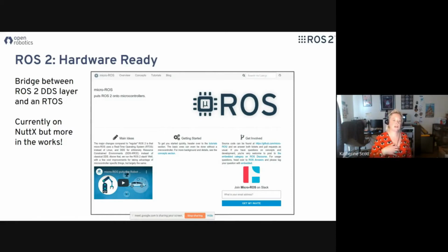And so within the past year or two, this project has started taking off, where you can basically build a baked-in ROS interface to all sorts of different kinds of microcontrollers. So if you're interested in, like, say, ESP32s, or some of the STM line of processors, you can deploy basically a little bit of code that creates a ROS interface to these hardware components. And I think this is going to be a really, really interesting and powerful feature in the next few years.